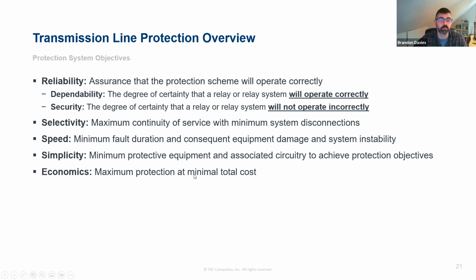So pretty much almost all of the time, you will see redundant protection applied at the transmission level. And that goes for almost any protection system, whether it's bus protection, transformer protection, and certainly line protection. And there's a really interesting IEEE guide that just came out, and I can probably get you the number if anyone's interested in it. But it's a guide on the considerations for redundancy in protection systems.